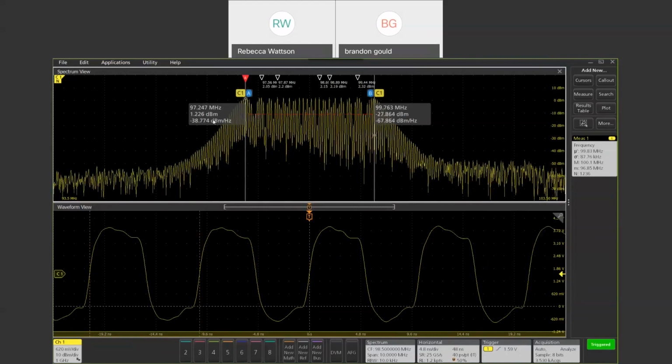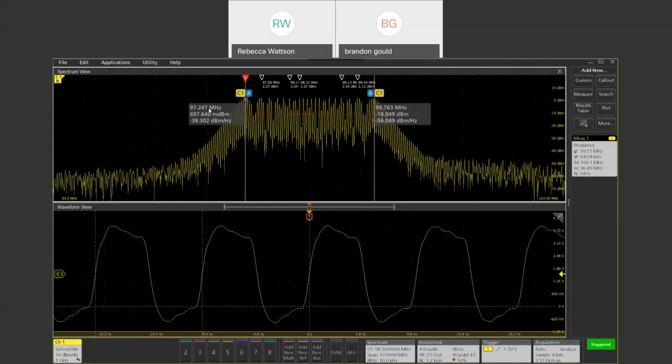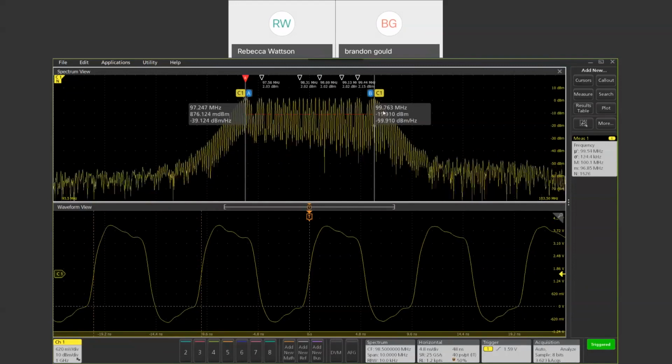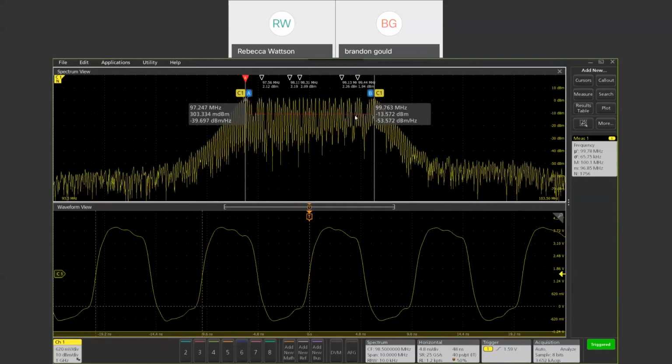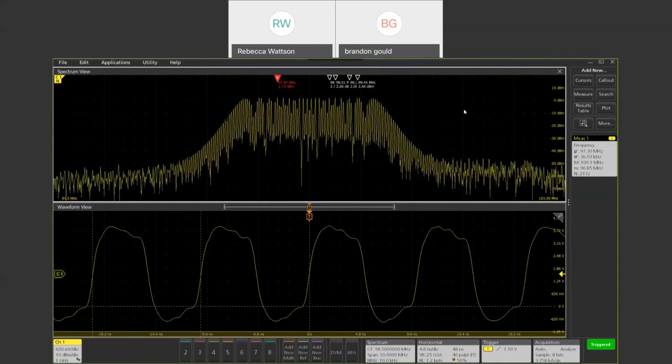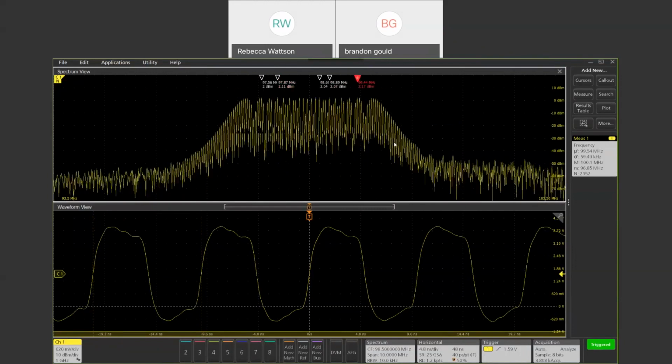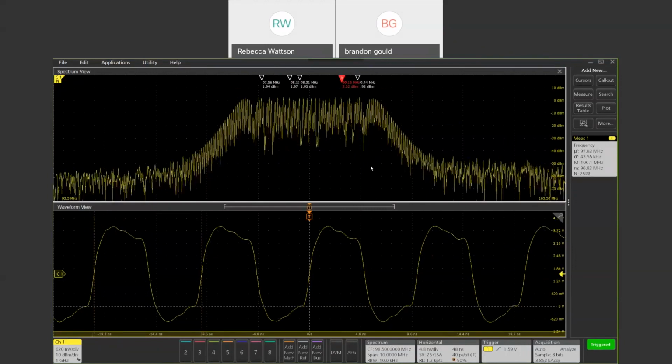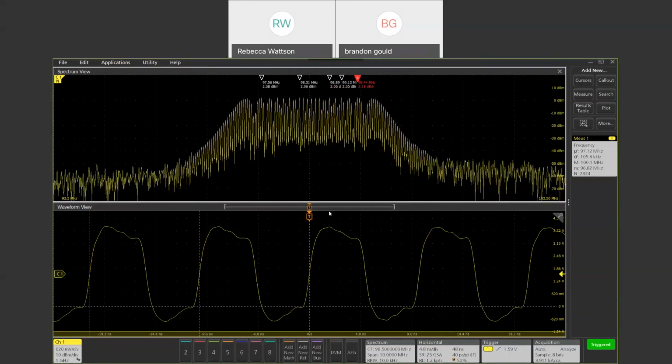Again, we're seeing down to 97 megahertz as the lower end of this clock behavior, up to 99. And it's fluctuating back and forth so that we can spread out the amplitude of this clock. That way we're not emitting any bad signals. Well, that's cool. We've been able to do that kind of analysis in the past with an FFT, right?